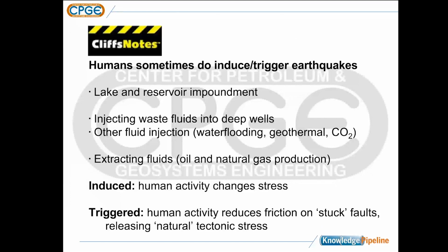earthquakes. They can do this when you're impounding lakes or reservoirs, if they're deep enough, a couple hundred meters or so. They can do it when they're injecting waste fluids into deep wells. Other kinds of fluid injection, like water flooding to enhance petroleum production, geothermal operations, and sometimes even CO2 injection. Sometimes earthquakes are induced when you extract fluids, that is, when you are producing oil or natural gas.